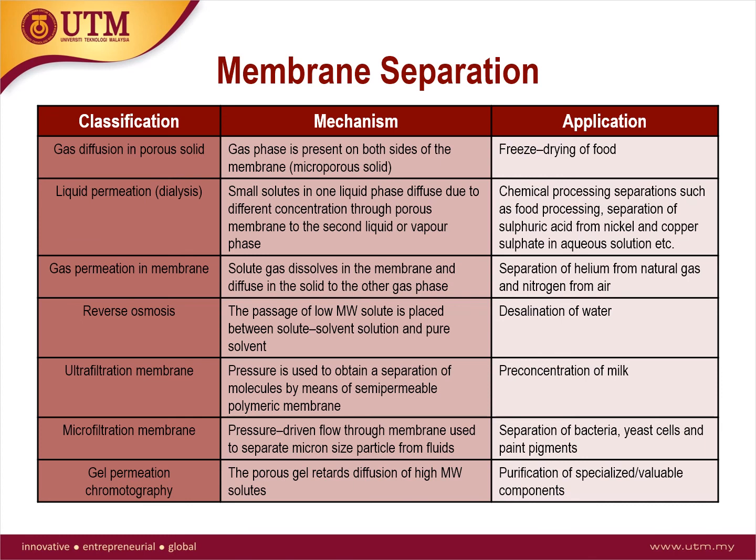Then the second class is concentration-driven operation, such as dialysis, vaporization, forward osmosis, artificial lung, and gas separation. The third is operations in an electric potential gradient, such as electrodialysis, membrane electrolysis such as the chloroalkali process, electrodeionization, electrofiltration, and fuel cells. The only type of membrane that operates based on a temperature gradient is called membrane distillation.